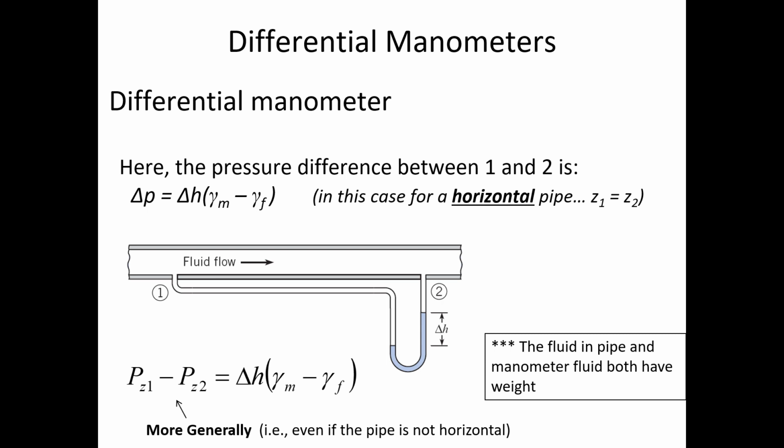Piezometric pressure tracks two things. It tracks what is the pressure at this location, and also at this location, what is our elevation above a datum that we're measuring all of our elevations against. And what I told you before about piezometric pressure was that inside of a tank, for example, if we have two locations in a tank, although the pressure is higher at location 2, if we go down through a fluid, the pressure increases, but you're losing z.